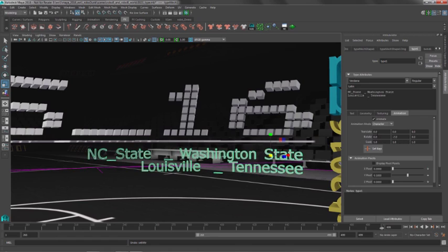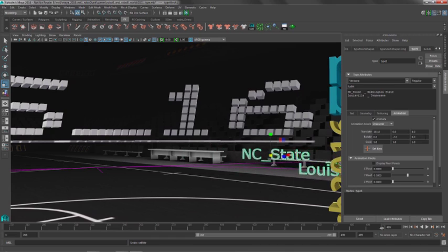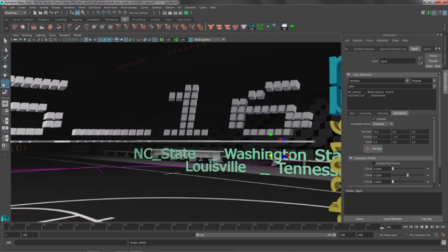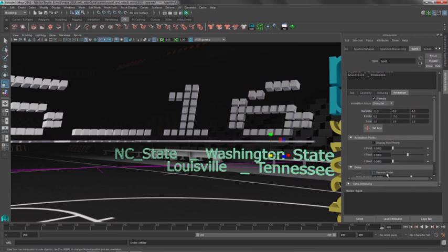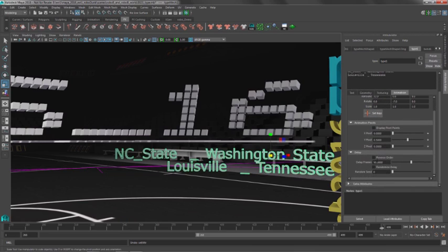So the next thing that we want to do is also use this text tool to animate the type coming on. The reason we're going to use the animation, the translations in the actual text tool as opposed to the global transform on the object is because the text tool has this really cool feature for doing a delay on each character built into it. And it's non-destructive. So if you change the type, the delays will just continue to work. It's very, very smart in the way it handles that.